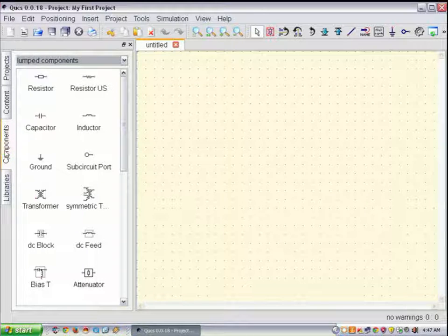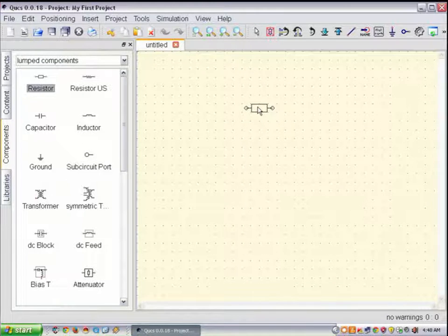I'll start with this simple resistor network. You find two symbols for resistor. One is the global symbol and the other is the one used by the US, what is known as the ANSI symbol. You can use either of these. I'll choose the global symbol, and once I click, the symbol will follow my cursor. It will place the symbol wherever I click on the schematic page. If I want to change the position, I right click and it rotates by 90 degrees. These points are the grid points, so it is easy to position the component. You can position this by left clicking your mouse button.